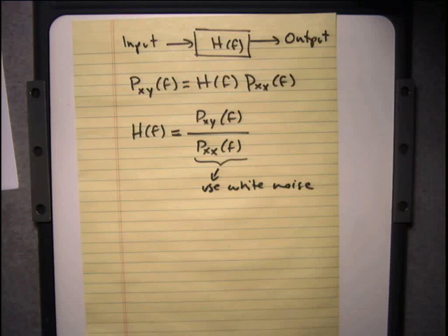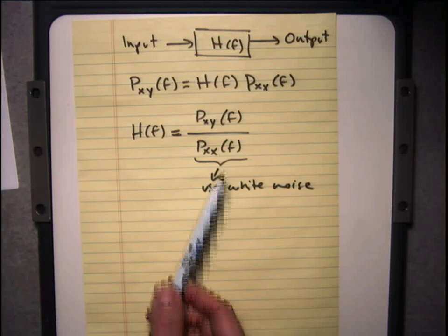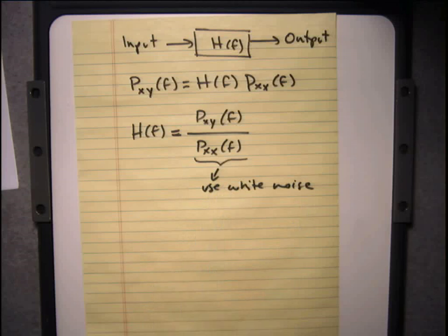This will work for very simple things, like little pieces of that system. But if you have a nonlinear element in your circuitry, which oftentimes you do, then this would not work. But it is a very interesting example of seeing where white noise is really the only thing that is going to give you all the information you want. You wouldn't think of using white noise. You would think of using some clever signal to put into that input so you can measure some clever output. You can do that too. Well, white noise does everything because it excites the system with every frequency possible. And so you're measuring the output everywhere across the frequency level.